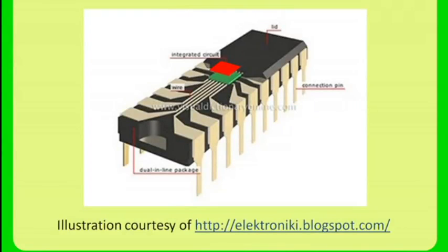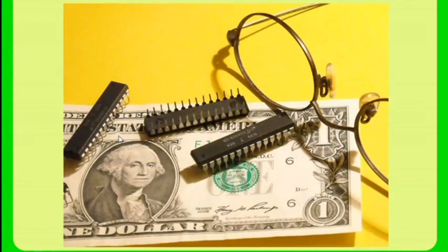Physical view of a chip, which you just saw on the prior page as one of these cut out complete chips, would be mounted on some sort of piece of plastic or ceramic metal like this that results in these leads that can be placed into a socket being connected to those connection points around the periphery of the chip. The chip itself would be small like this.